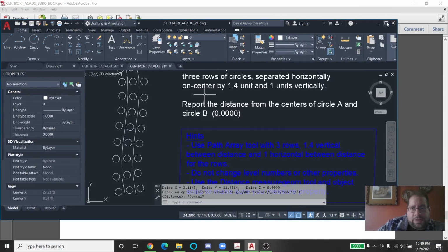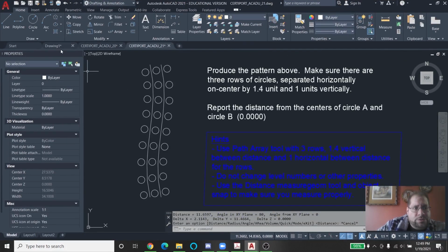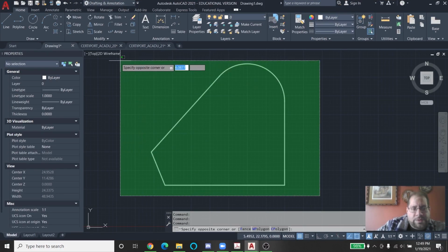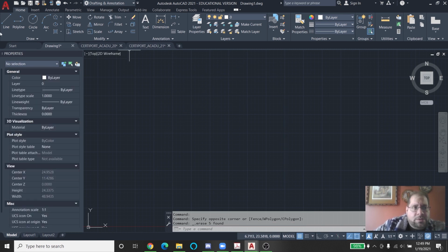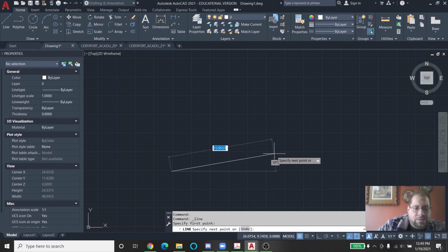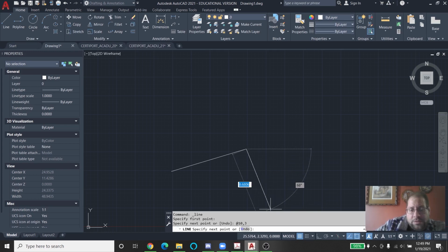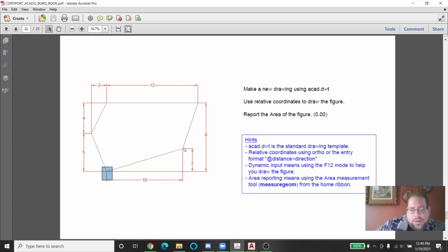Let's get a new file. Or I'll just use the same one here. Let me erase this. Okay, so pick a line from here. I'm going right 10, comma 3 for up. So that's the first line. Next line appears to go from 3 to 9, so that's a height of 6. And how far to the right does it go? I can tell that pretty easily.